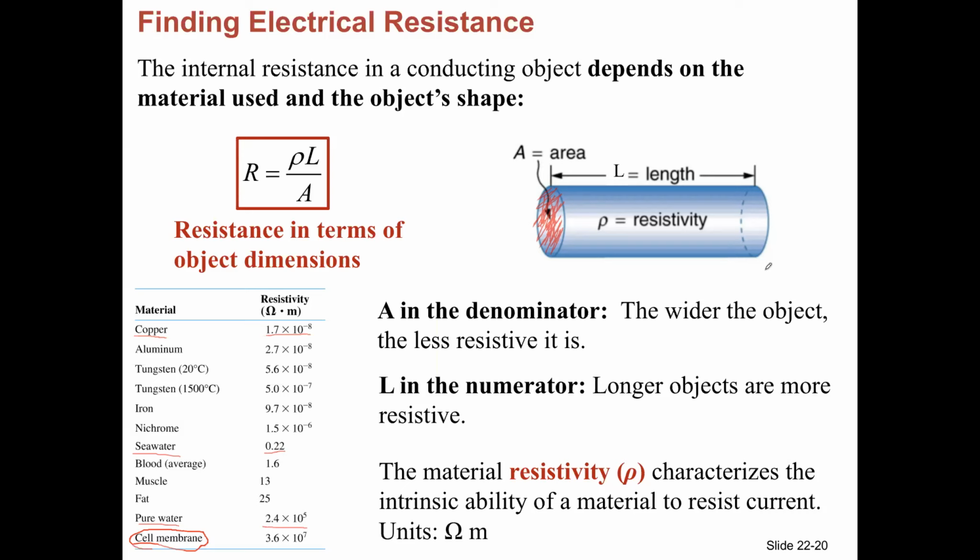And then another question from Brody. What causes the material's intrinsic resistivity to increase? For instance, why is tungsten less resistive at a lower temperature? That's a really good question. Basically your intuition is kind of correct. It depends on the amount of collisions the electrons experience.